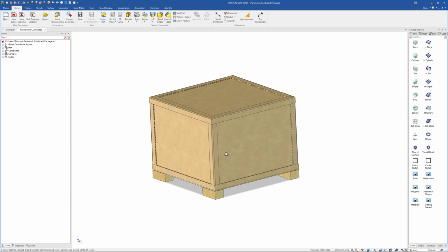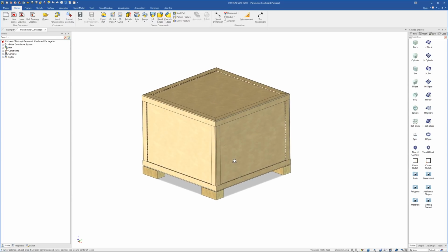It can also help when you're selecting multiple IntelliShapes. So if we go around here and we select down to this IntelliShape, and to start here, I'm going to say I'm not using the Alt key. And then I hold down the Shift key here. It's actually quite hard to select onto this next shape holding the Shift key because it's part of the other assembly. Whereas if I'm holding down the Alt key, and actually these are a pattern, so a better example would be one of these shapes.